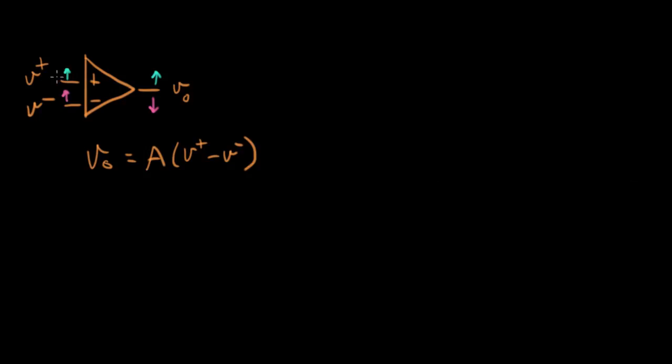Let's say that the positive input, the non-inverting input, went down this time. That means V out will go down. And let's do the same thing for the inverting input. If the inverting input goes down, what does the output do? It goes up. It goes in the opposite direction. That's a way to think about this symbol when you see it on a schematic page: how do these signals translate through the device? Non-inverting signals go in the same direction. Inverting signals go in the opposite direction.